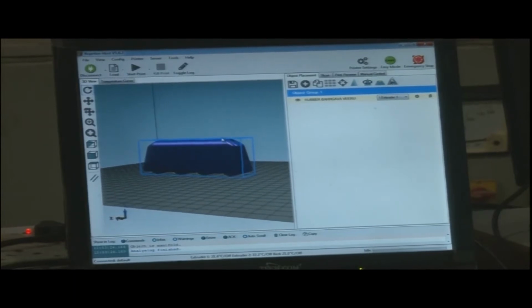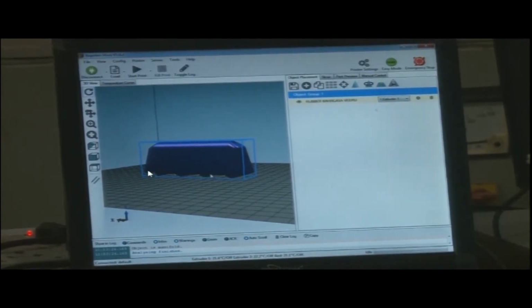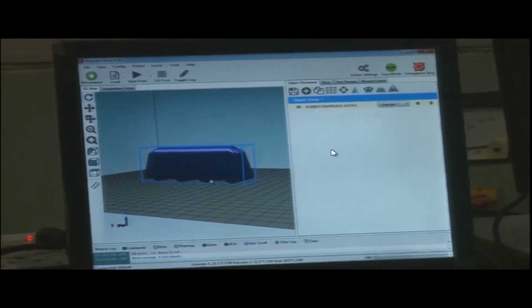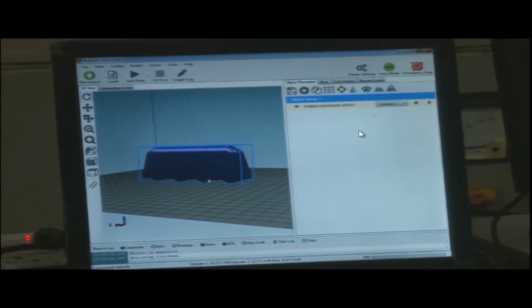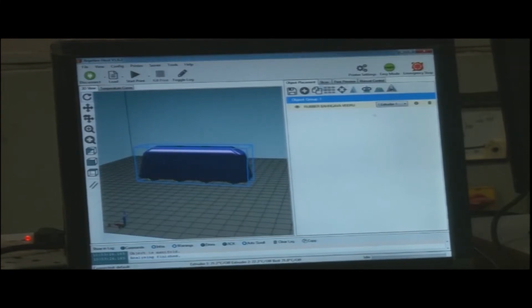The height of the entire job will be cut into a number of slices. How many layers there would be, the machine would decide. So we have to program in terms of slicing, and the machine will deposit one slice in one stroke, and this will be deposited layer by layer and finally becomes a complete job.